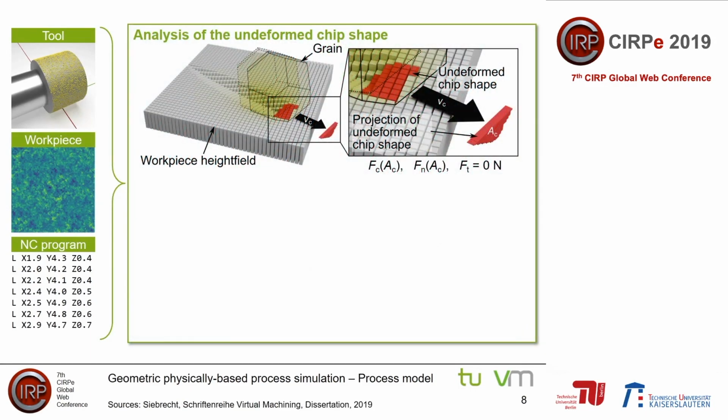In order to calculate the process forces, the undeformed chip shape of each grain engagement was analyzed. Using an empirical process model, the process forces were calculated based on the undeformed chip area.